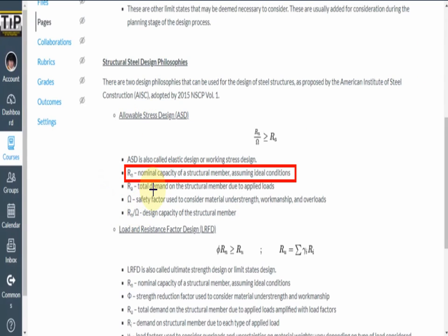If axial tension or compression, you will be able to determine its axial capacity. Same thing with shear and all. No? So this one, we usually get using the code specifications. No? So depending on the action that you consider, this may be different. Okay, so this will be different in tension, in compression, in flexure, etc. Okay.